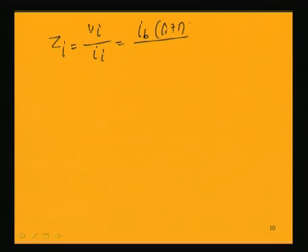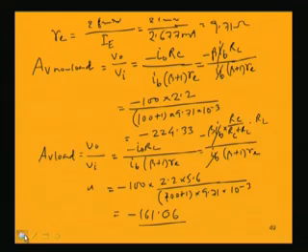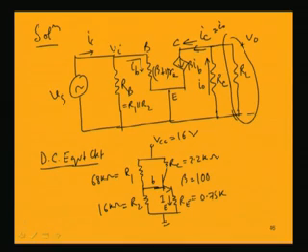Now, what is input impedance? That is known as Vi by II. Vi is IB into beta plus 1 RE and II in the denominator. So, IB can be again written as, if I look into the circuit, IB is equal to II into RB by RB plus beta plus 1 RE.